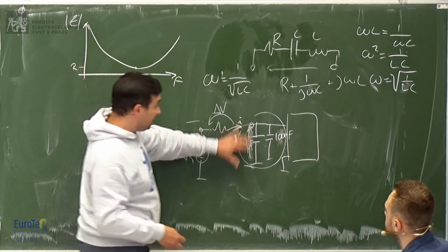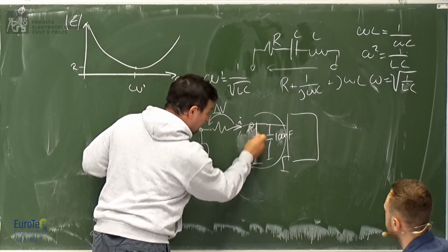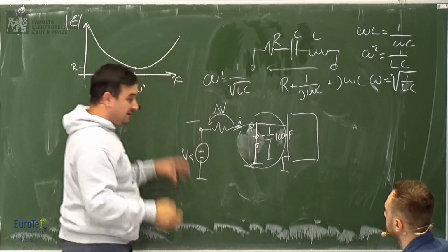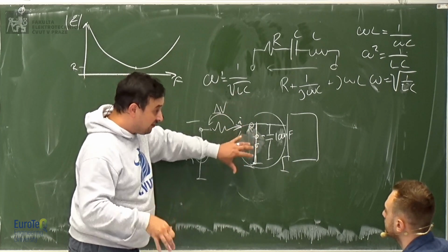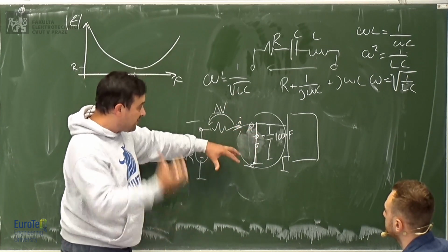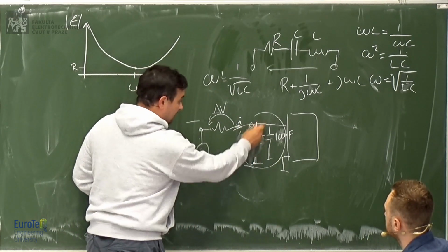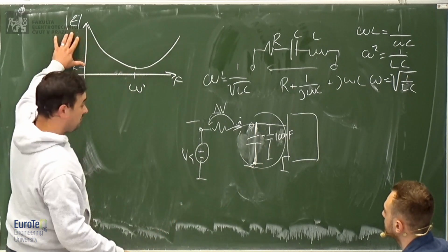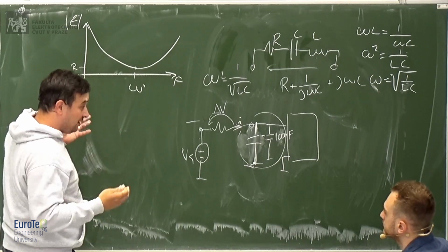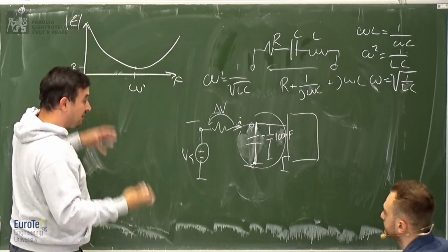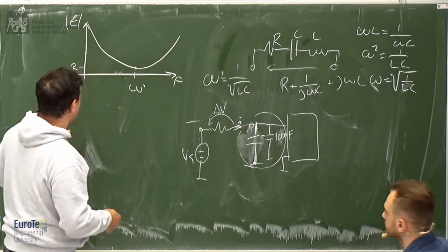This would be 0, which means that only for that frequency you get a short, which suppresses the voltage at that frequency, because the capacitor behaves like a short circuit. Whereas for 0 frequency, it's infinite, okay? So that's the beauty of the capacitor, which behaves selectively as a short circuit for high frequency, suppressing the voltage because it imposes a short circuit there.